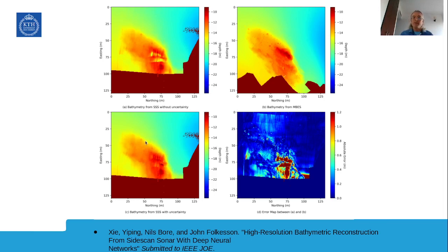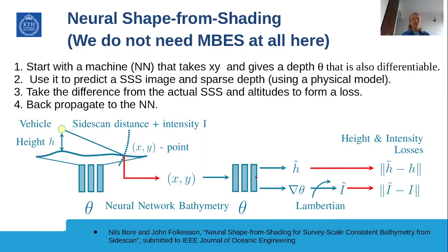So that estimating uncertainty did help, and fusing the data, of course, helps a lot. And then here you can see the actual errors. Like I said, the average error is super small, like you saw on the previous slide, because of these big areas here with blue, but then there are some areas that are getting up in the reds, and you can see 1.2 meters error there in those areas. So that'll give you a good idea of what it's able to do.